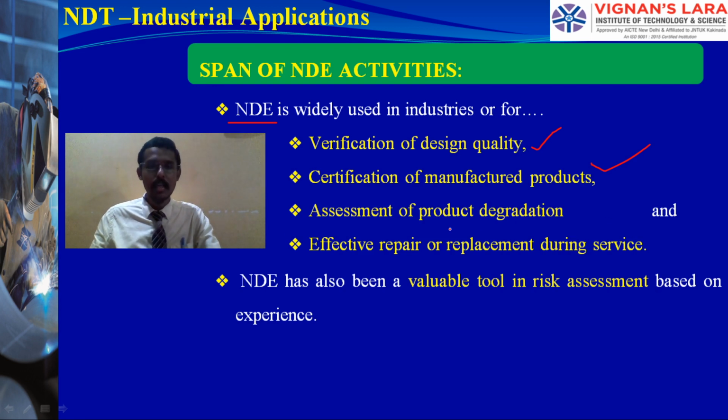Then also assessment of product degradation: how long it takes for a crack to occur again, always in service, in a building, how long it will survive. Those things we can also judge, whether the discontinuity is within the permissible range or not. If it is not permissible, we have to reject. So a range of assessments and interpretations we can do with this.